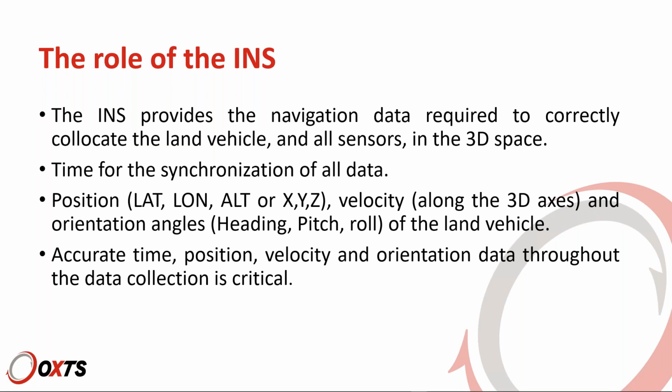Position, either in global coordinates, lat, lon, alt, or if you have a local coordinate system set, X, Y, Z. Velocity on all axes and orientation angles, heading, pitch, roll of the land vehicle. Obviously, it goes without saying that having all of this measured accurately throughout the data collection is critical. So the INS needs also to guarantee integrity and solidity of the data.